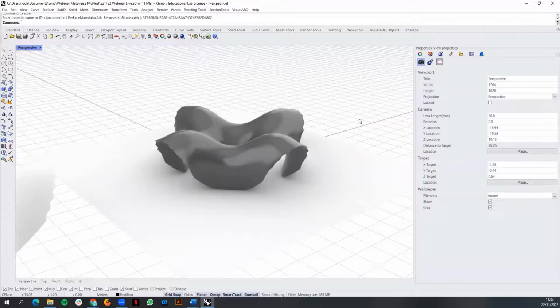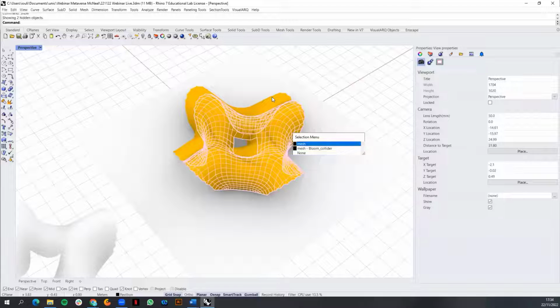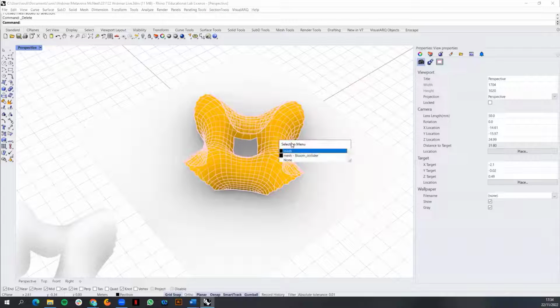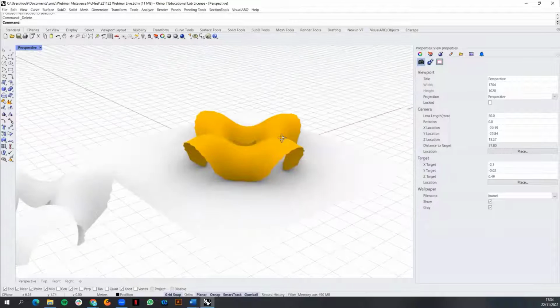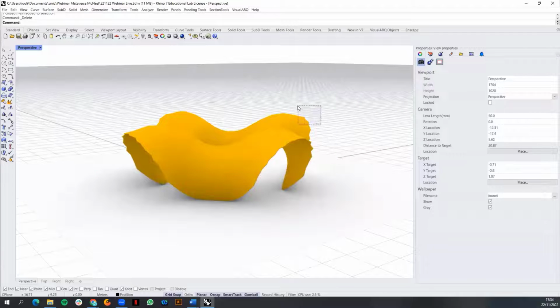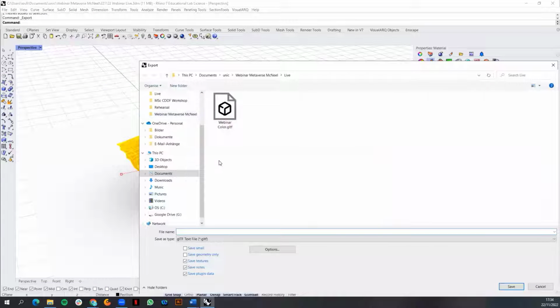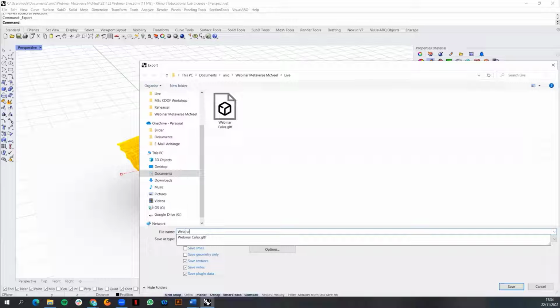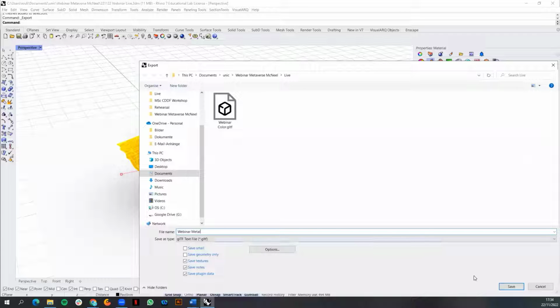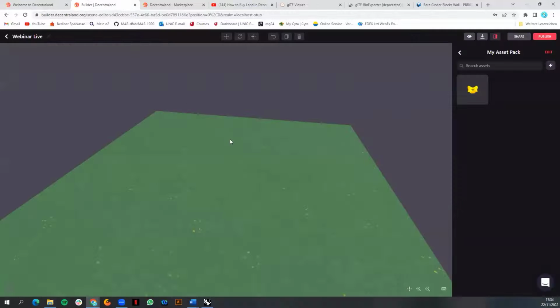So we can export now again. Sorry for that, I have something extra there. So I have basically my mesh and my collider in one. Now it seems orange because of the collider, but it will be invisible once we export it for Decentraland. So I'll select both of them. And I will export my selected file, again as a GLTF. And I go back to my builder.